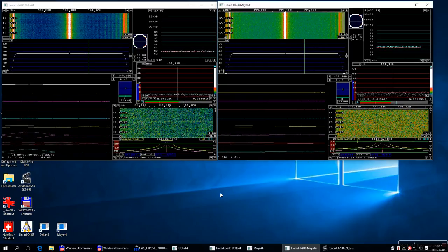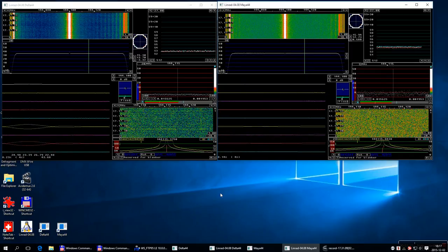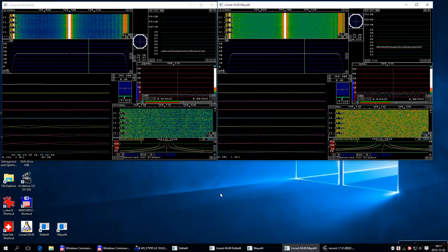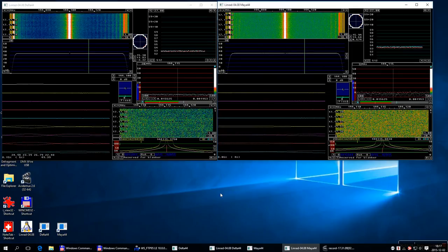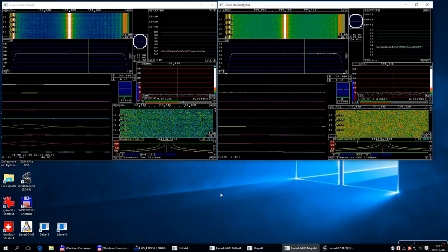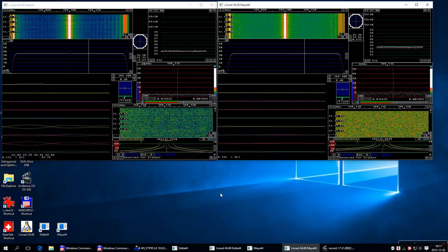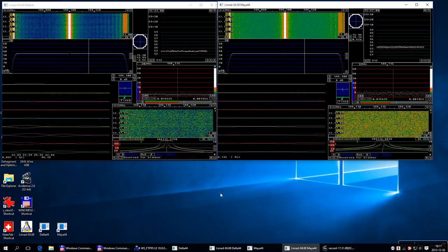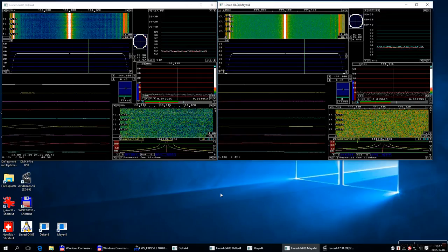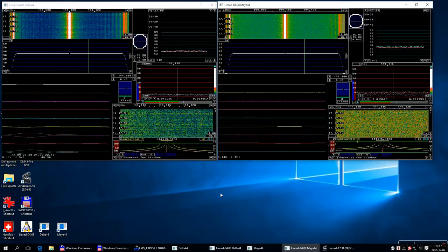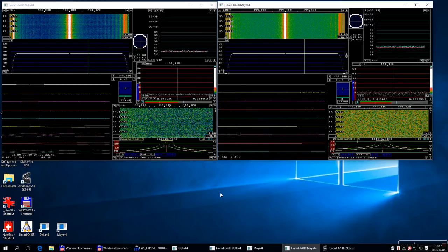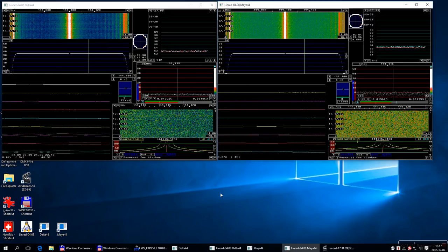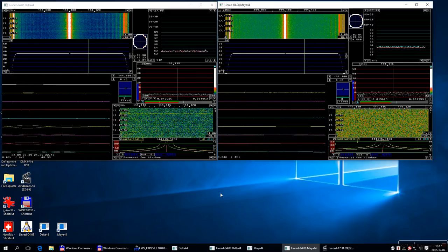You add the LNA, which adds some noise, and the noise floor would go up from S3 to about S5 or S6, because you want the noise from the LNA to dominate completely. So that means listen to the quiet sky and set the S meter to show S1 on the noise floor at SSB bandwidth. That's how to calibrate the S meter, in my opinion.